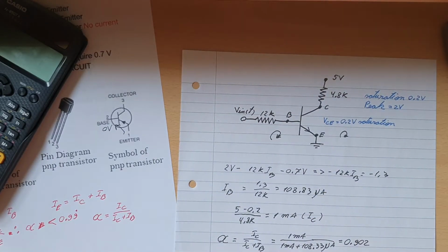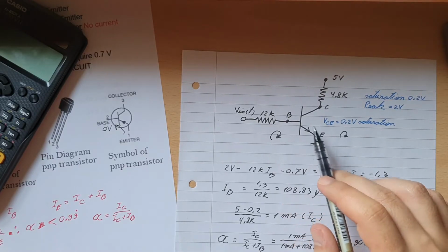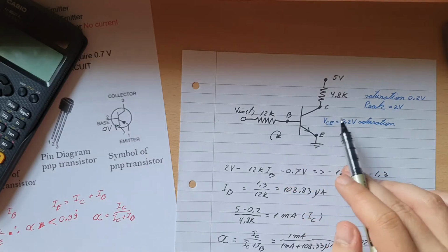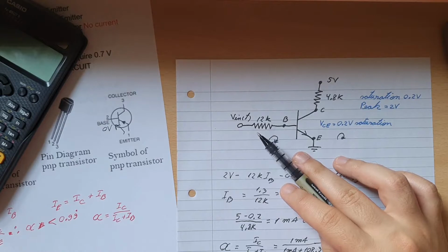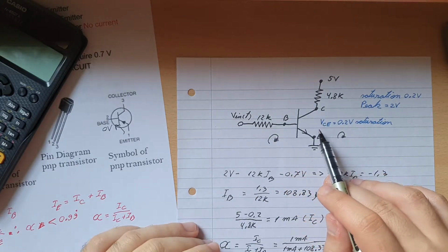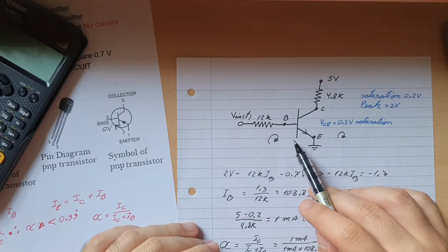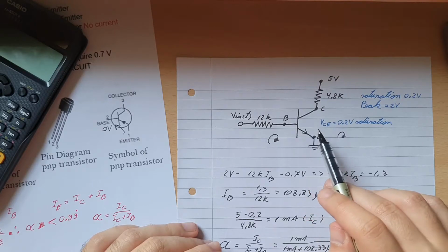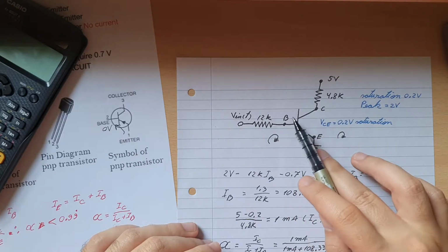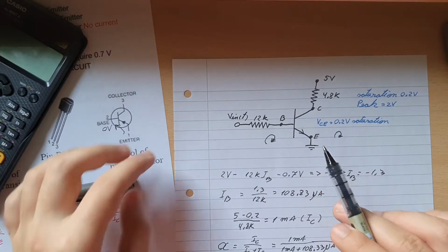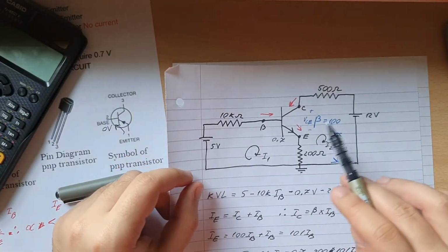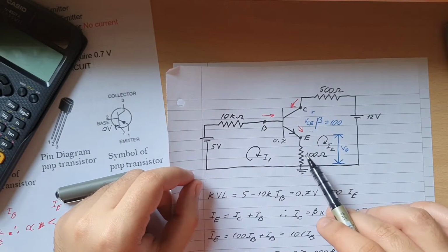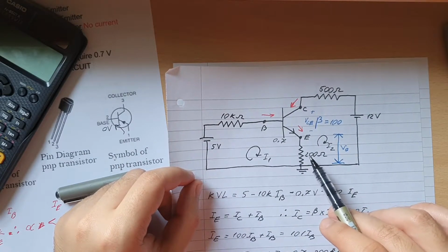Now the trick about this one is that we know the voltage input, which we know for the other ones as well. It's kind of curious. I guess the only reason why this works here, but wouldn't work in a previous example like this one here, is because we don't have any voltage drop going through the emitter.